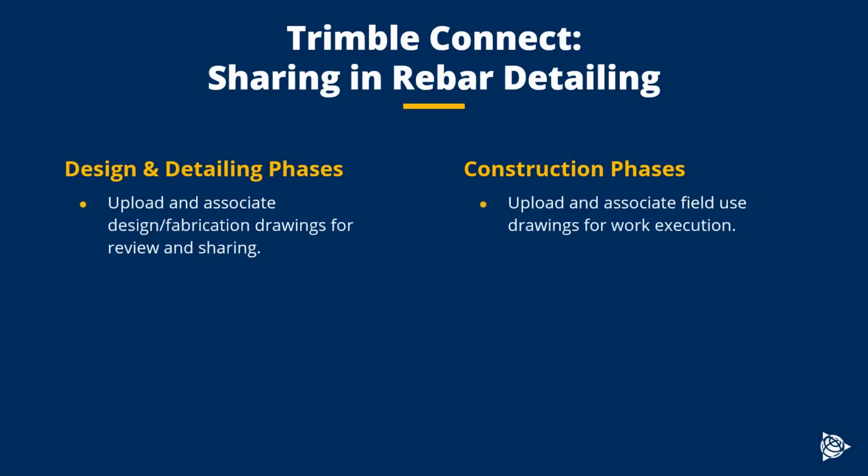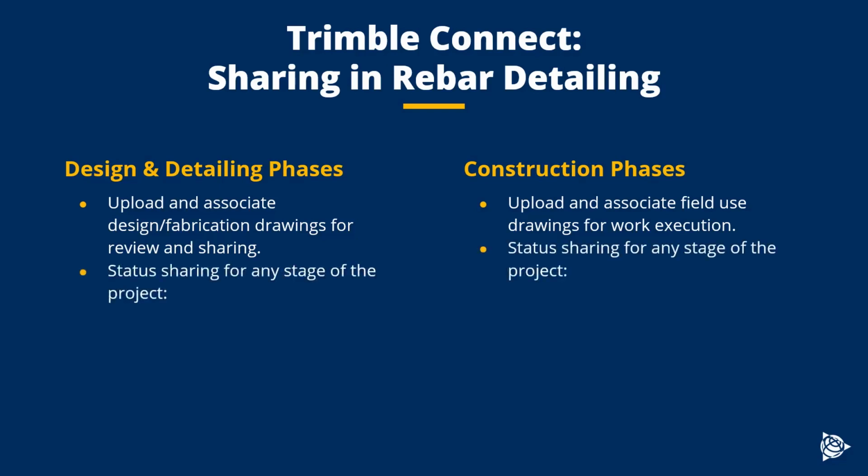Now, another thing about sharing is we're able to associate the documents we create, either reports or drawings or so on, with actual objects in the model or Trimble Connect directly by clicking on those objects and then viewing that documentation. Now, we can do this manually by uploading a document to Trimble Connect, finding an object, right-clicking, and then associating.